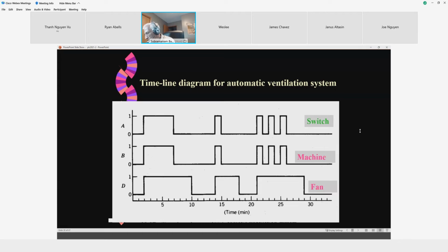So for example, if I locate a temperature sensor inside as the machine is running and the heat is building up, well, you keep the fan going, but measure the temperature. If the process was shut down very quickly, obviously the temperature would not have risen. So use the temperature sensor to control the time element. Can be done, okay? But not in this case.